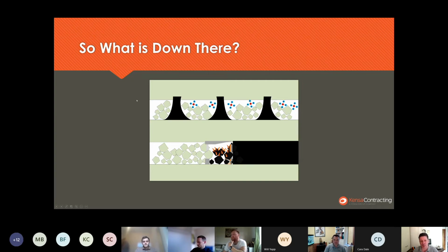At the top here, we've got an older mine. These things can be stacked on top of each other. There can be many seams that have been worked over the years at various different depths at any given location. An older mining technique would be to leave piers of coal in and dig around them to extract the minerals. They would have dug all that out, abandoned the mine, and the voids would have collapsed. So to some extent or another, the ceilings of these things would have collapsed. And so what you've effectively got is a bunch of rubble at some depth mixed in with coal.